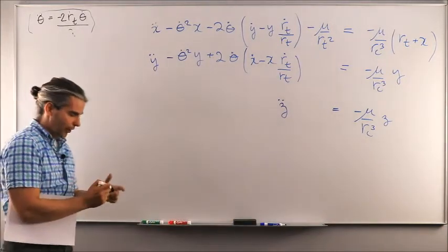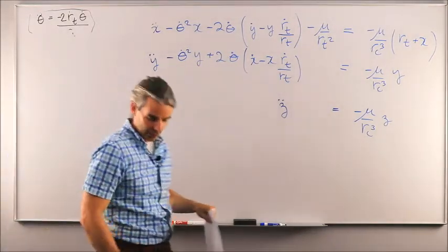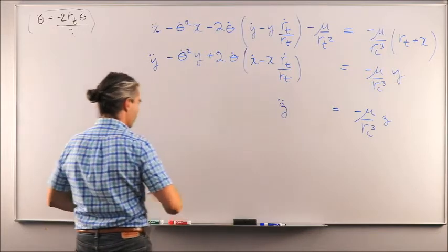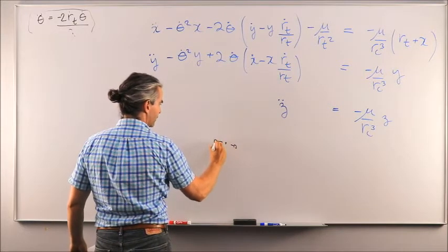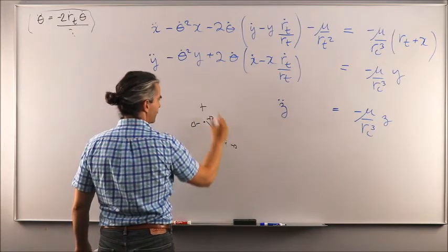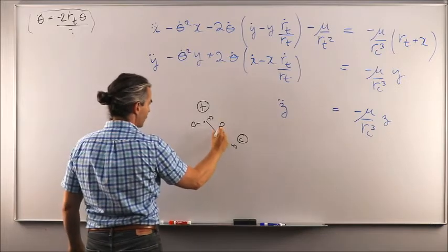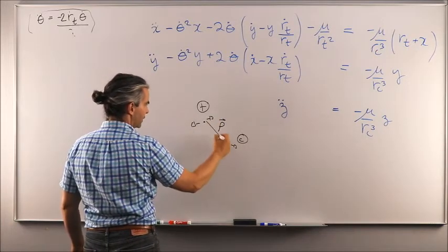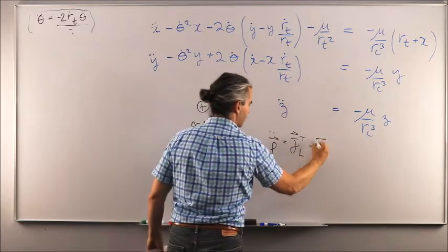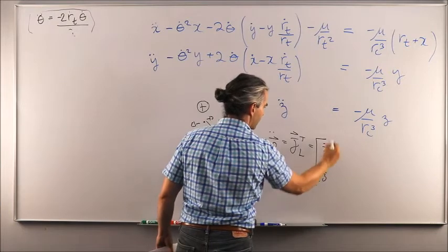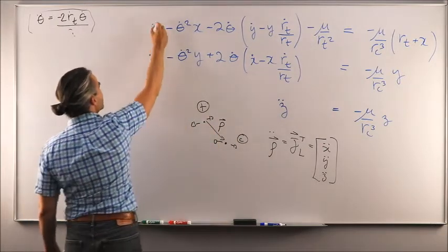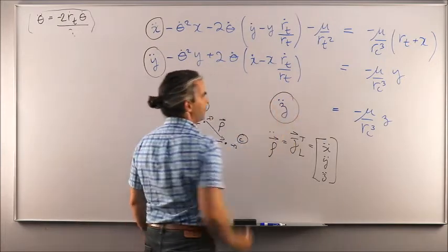Wow. Aren't those equations beautiful? Yes, and that's why I like formation flying quite a bit, because the equations are so elegant, okay? So if what you want to know is how this chaser spacecraft accelerates away or towards the target spacecraft, T target, C chaser, relative position, then time derivative, relative velocity, and ultimately relative acceleration in LVLH equal to x double dot, y double dot, z double dot, right? This is what we're looking at. How does this chaser spacecraft accelerate away or towards the target spacecraft? All you have to do is solve those three equations for these three quantities, and boom, you get your answer.